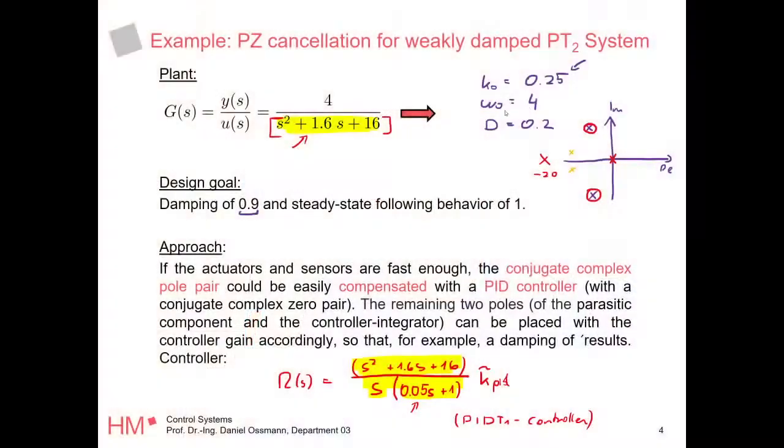So please don't select it at -4 and -8. A factor of 3 or 4 or 5 is usually good. And as we have this pole here at the frequency of 4, so this guy here is actually a little bit less than 4. Far away from your system dynamics is a good idea.